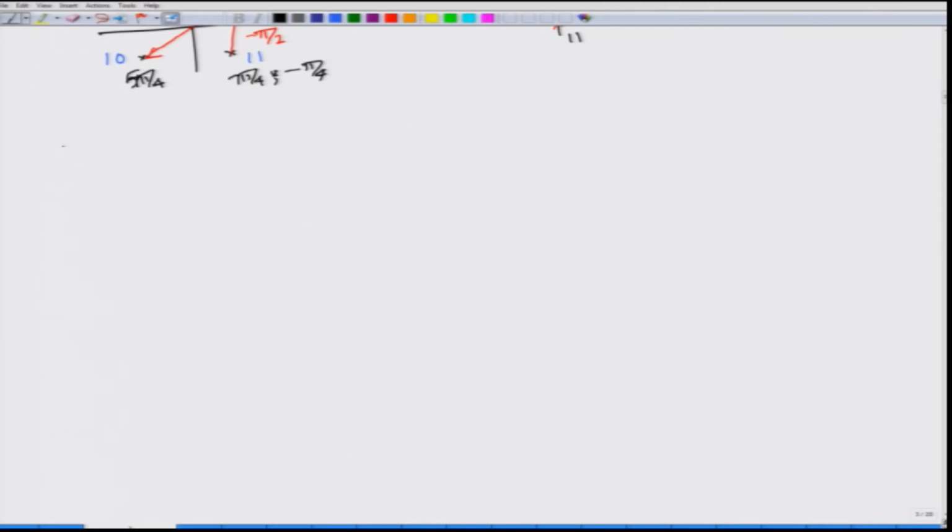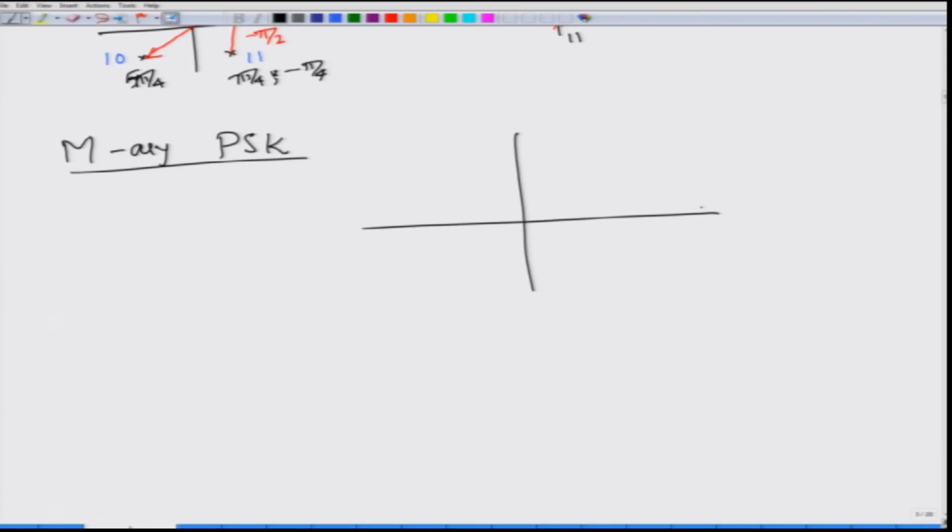One final modulation that we are going to discuss here is called M-PSK. The idea behind this is very simple. You go to the constellation diagram over here. It could be the phi 1 and phi 2 space, or equivalently the I and Q space. Phi 1 and phi 2 is the real 2D space, whereas if I use I and Q, that would be one complex symbol space. So, this gives me complex symbols, this gives me real symbols. These are just ways of representing them.